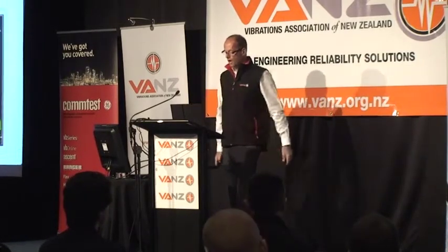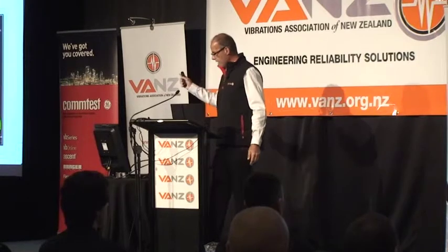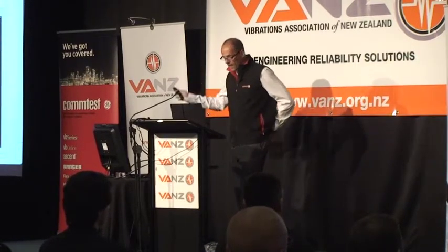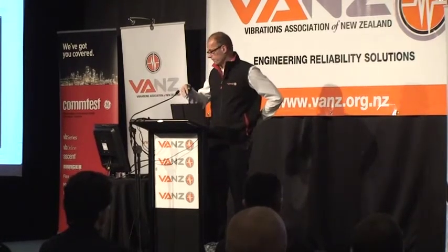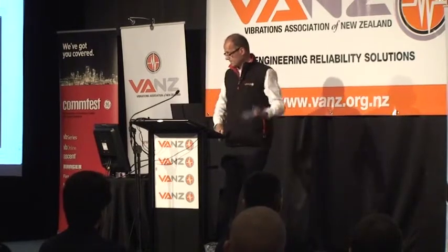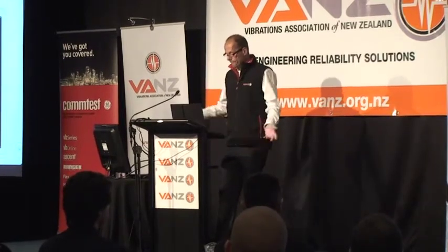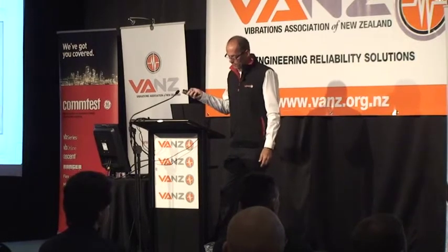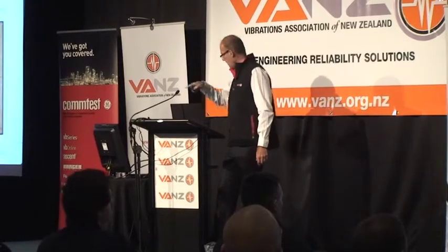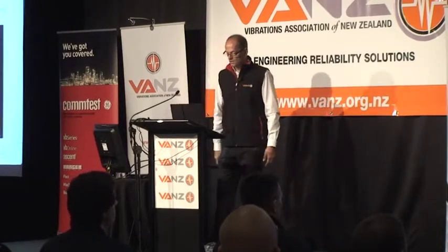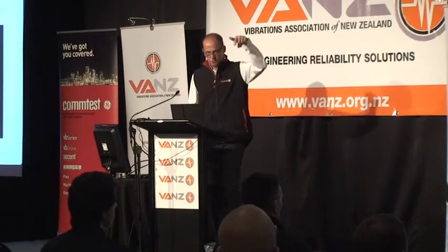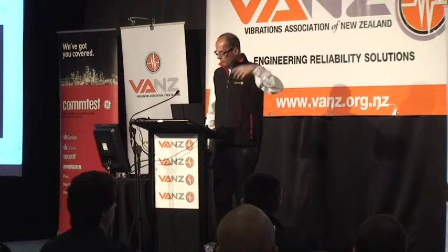But in this case, when we took a higher resolution measurement, we saw that around the peaks there were actually these sidebands. And that is a classic sign of broken rotor bars or cracked end rings or something like that. So I said, well, that's what the problem is. And so they took the motor out, and as you can see there, all the marks around there were quite a few damaged areas, but that's what they saw. So that problem made the spectrum change in that way, and we were able to detect it.